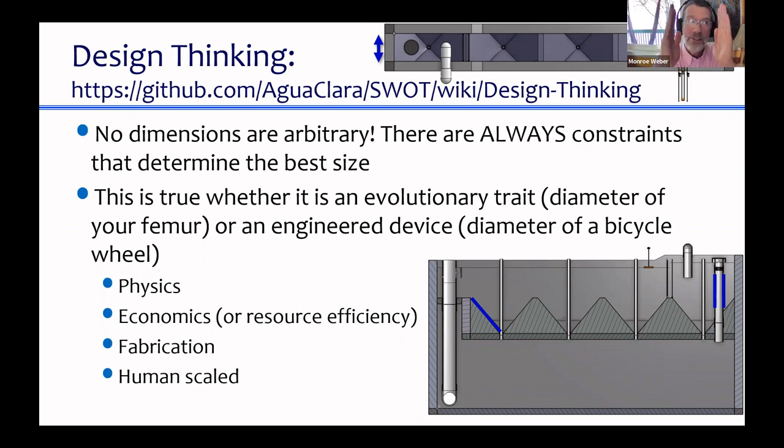So a shallow channel can be fabricated when it's hand wide, but once you have to actually get your whole body in there, then it's the dimension of your hips and maybe a little bit about how much your elbows have to move around while you're fabricating that ends up setting how wide is reasonable before the masons that have to fabricate this start complaining about how this is impossible to build. And believe me, those are issues that you absolutely have to think about when you're designing things. If you design something that can't be fabricated, you're going to be famous on the job site, and you don't want to be famous on the job site in that way.